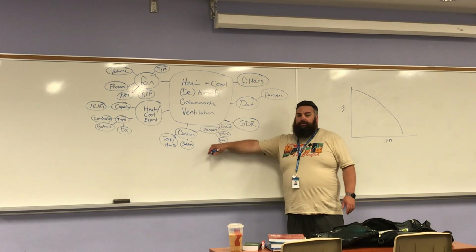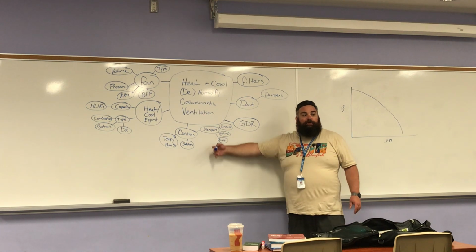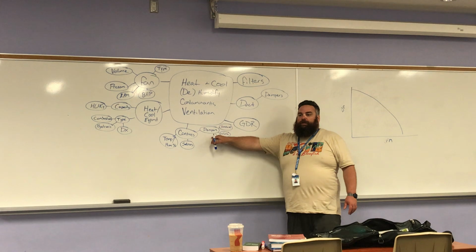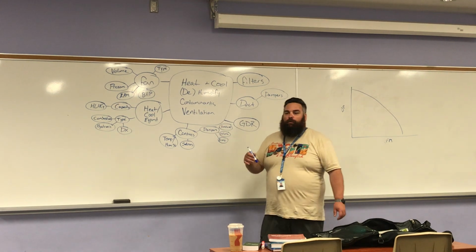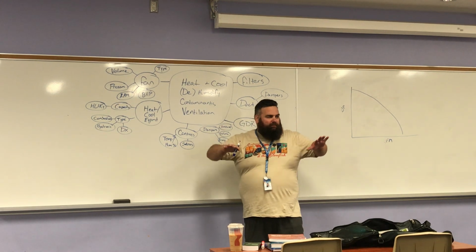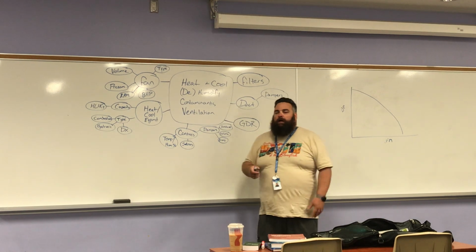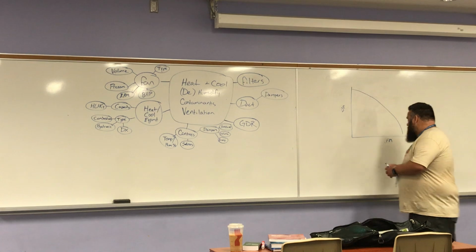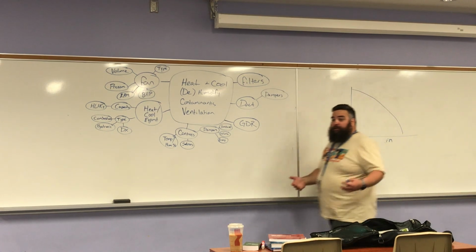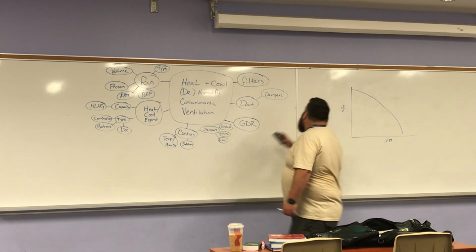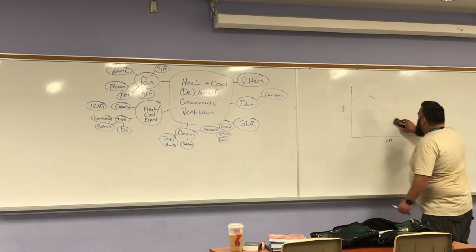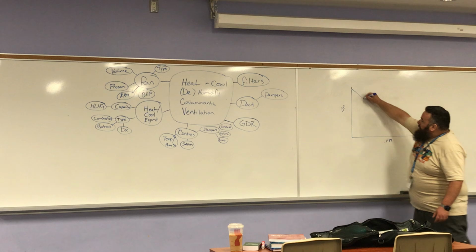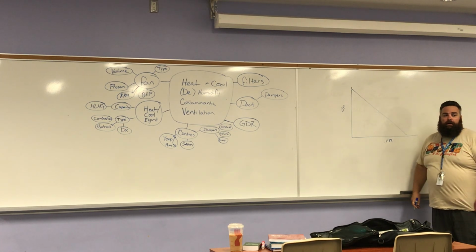Just as an aside, I designed a makeup air unit once from scratch, and when it came to the dampers, we actually had to look at what's called damper authority. This is a little bit more than you need to know here, but controls, and we might see this in hydronics, are not necessarily linear. You'll have a linear control that, using the same chart here, this would be an example of a linear damper.